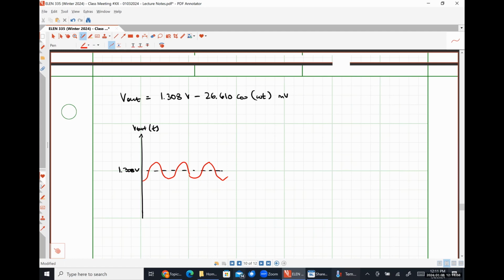But with a transistor amplifier like this, until we do all kinds of design and signal conditioning, our AC signal is actually going to be superimposed on that DC operating point for our output. And so we're going to have to employ techniques in order to drive that operating point closer to zero so that it gives us the output that we're actually expecting, or that we're acclimated to have with our current level of experience.